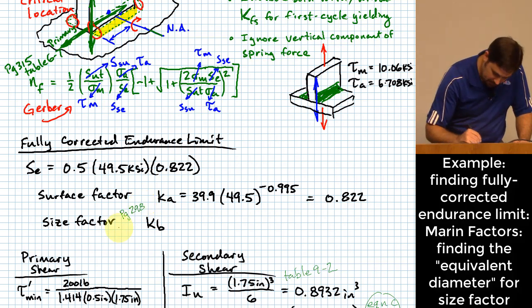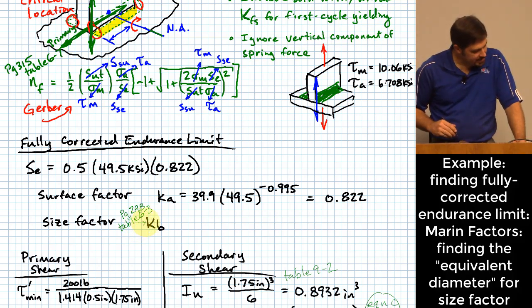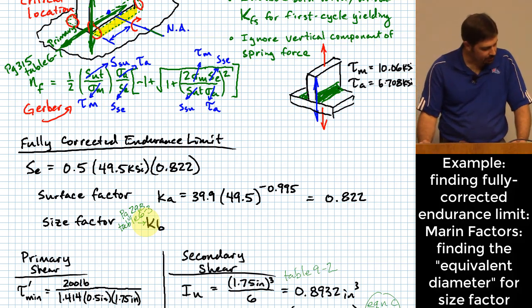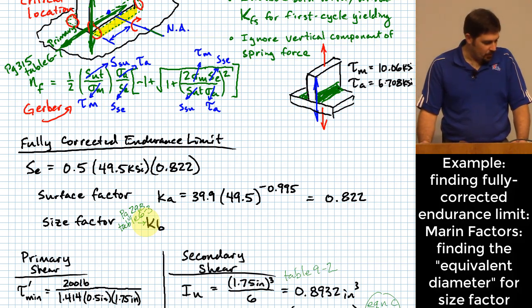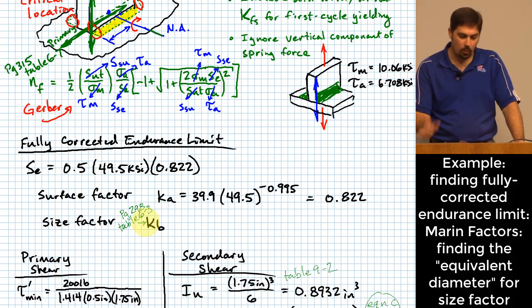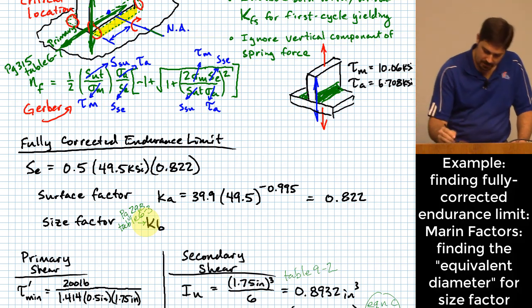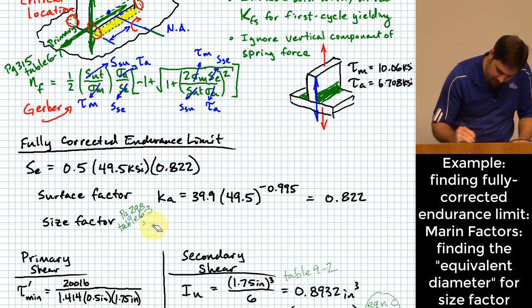And it's in table 6.3. What we have for D sub E there is 0.808 times the square root of HB for a rectangular shape. We have basically something very similar here. It's just that we have two rectangles, and so we're going to want to take the weld size and multiply it by 2. So first, before I do K sub B, let me do D sub E.